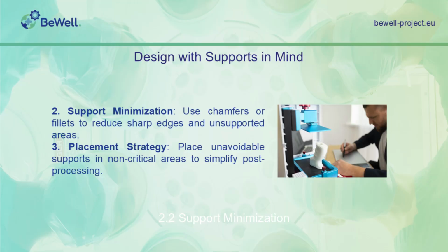2.2 Support minimization. Add chamfers, angled edges, or fillets, rounded edges, to reduce the need for supports. Adjust the geometry to avoid sharp transitions or unsupported areas. 2.3 Placement strategy. If supports are unavoidable, position them in non-critical areas where post-processing won't affect functionality or appearance.